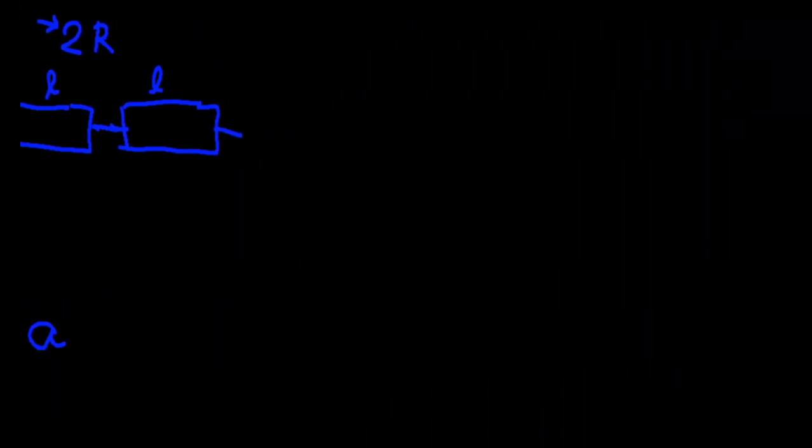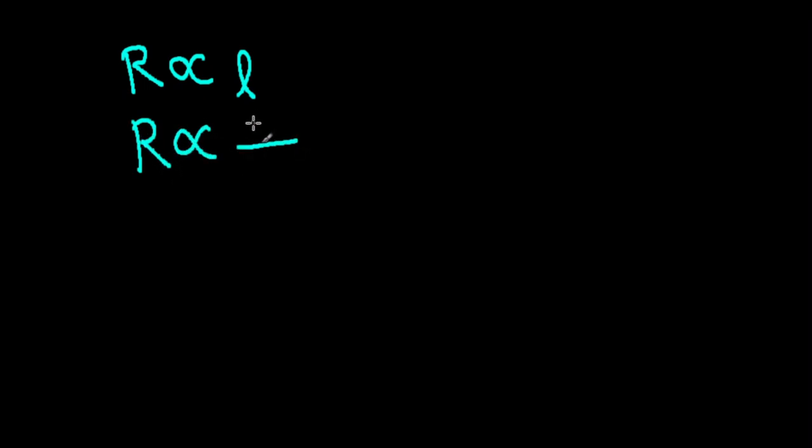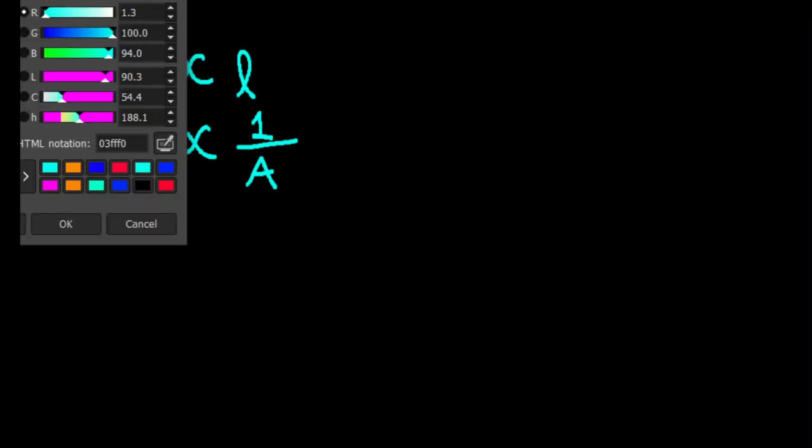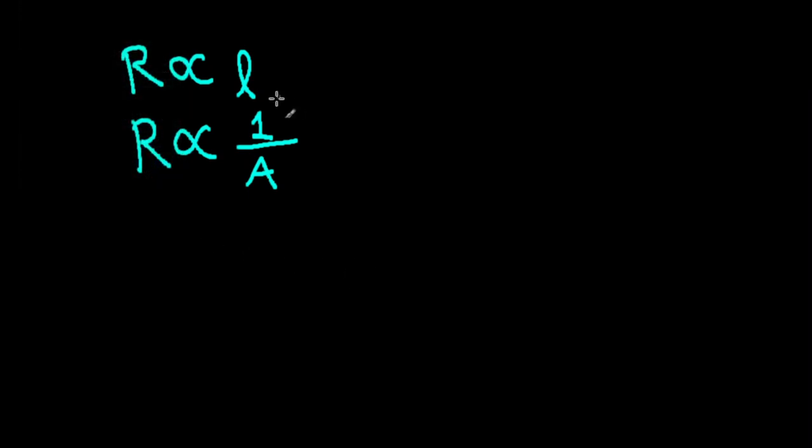Let's actually develop this a bit more. So resistance is proportional to length, and we know that the resistance is inversely proportional to the area. If I combine these, I should be able to say that the resistance is proportional to the product of these.